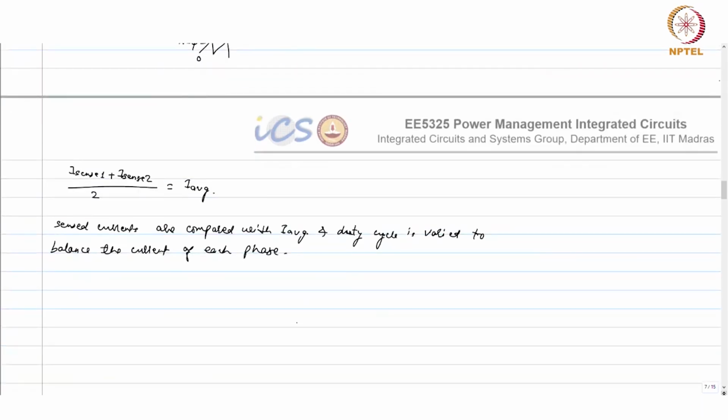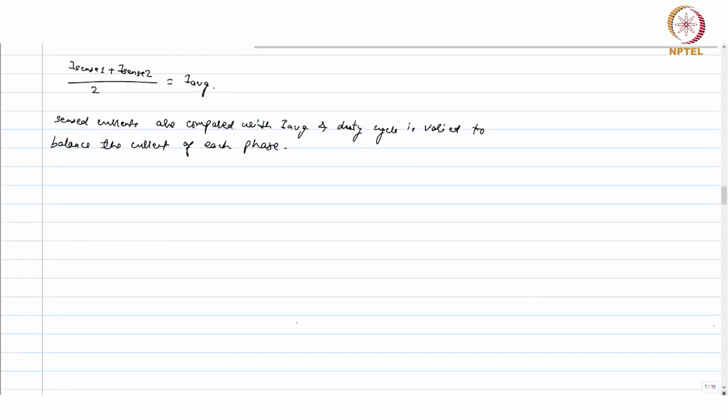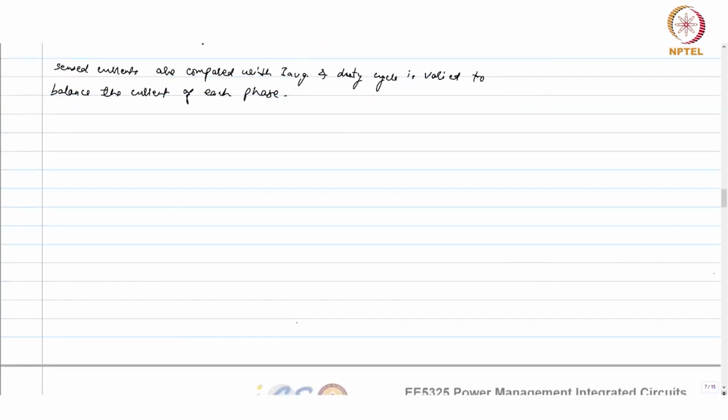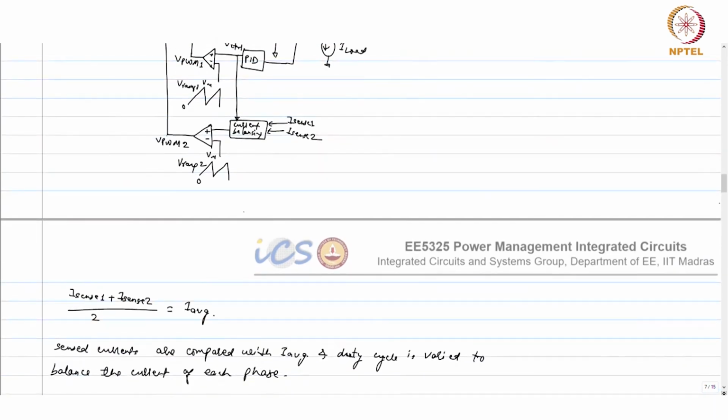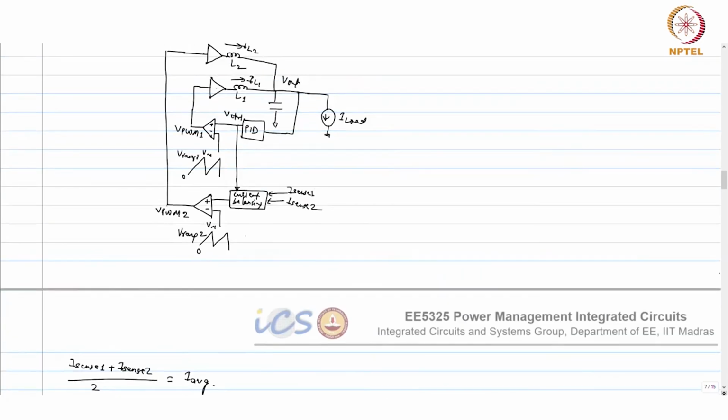Okay. So you can subtract, add depending upon if you know how much it is required, or it may have its own integrator also, because you are comparing something, it will generate an error. That error can be accumulated and digitally you can correct the duty cycle, or you can implement it in an analog way and add or subtract the voltage from V control, which is going to the comparator.